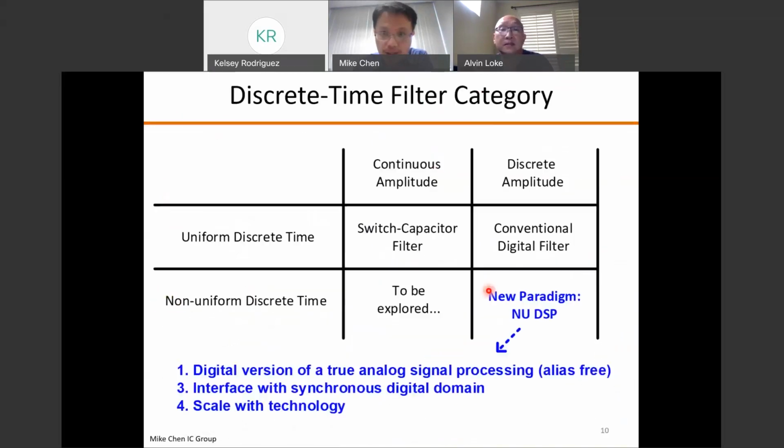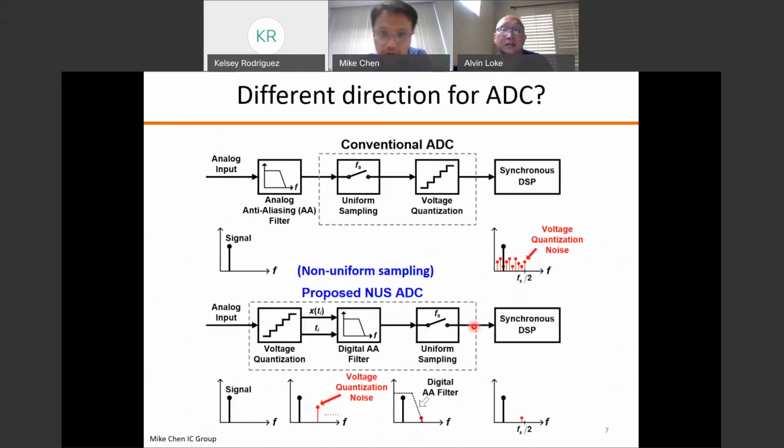Sure. I believe the biggest difference is that what we have been going after is really trying to convert back to uniform samples. In continuous time processing, as I pointed out earlier, whenever they have these pulses, the sample events get generated and they actually combine in an analog fashion. You combine those pulse energies, and the output is still analog-ish, an asynchronous waveform, as you can imagine, if you just sum up those non-uniform sample points.